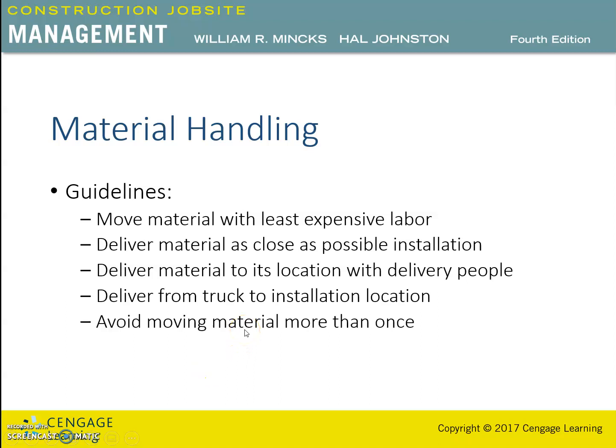The next guideline for material handling is to avoid moving material more than once. This is a situation where we can try to optimize things. When material is stored or stockpiled on site, it should go from the storage area to installation.